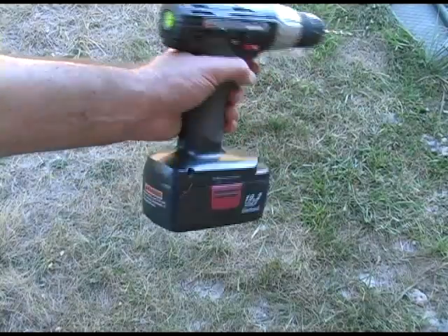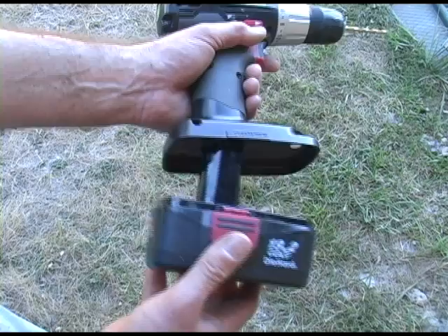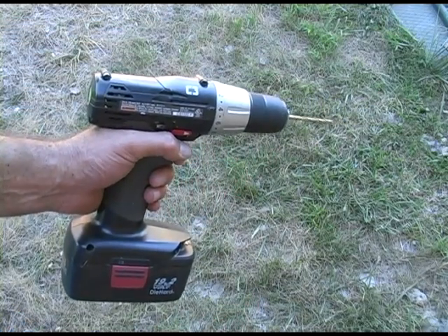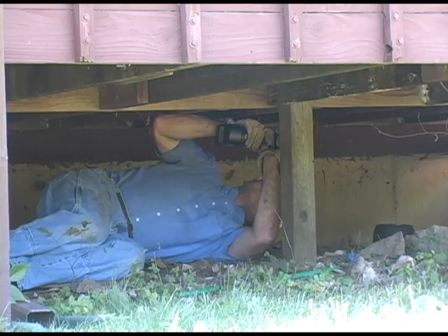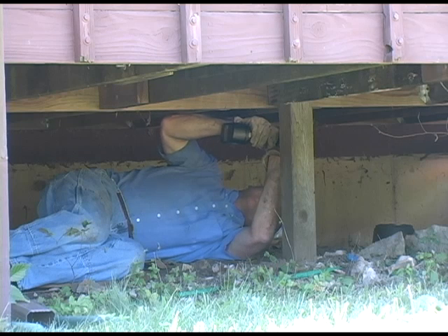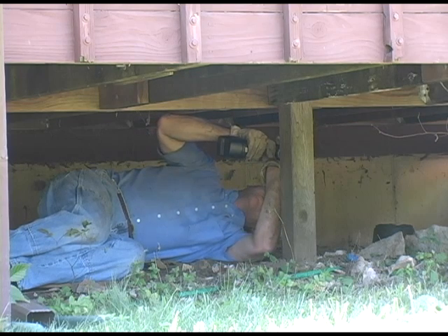To reduce the risk of electrocution, we can substitute a cordless rechargeable drill such as this. When used according to the manufacturer's instructions, the drill's low-energy battery is unlikely to cause a serious electrical shock even when the worker is in full contact with grounded surfaces.